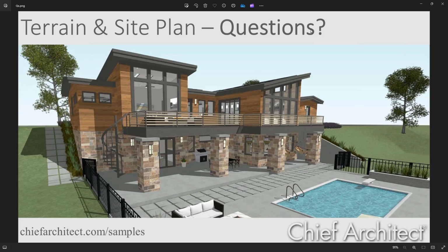I have a model where I imported a site plan, drain perimeter and contours, on my main first floor level. The house came in fine, interacting with grade, but in the renovation design I needed to add an exterior stairwell, obviously at the basement level. I have a real hard time getting grade to cut square and tight to the basement retaining wall coming out. What is the best approach to get this square opening cut into grade right adjacent to the house for the stairwell?